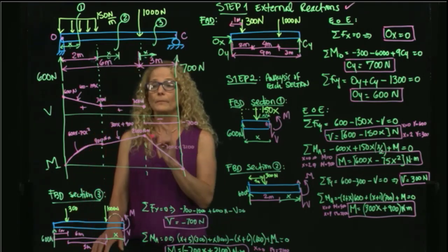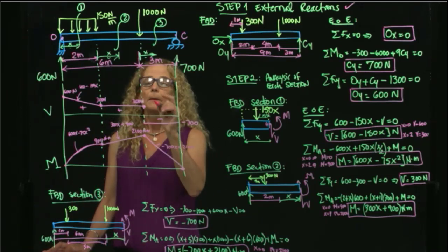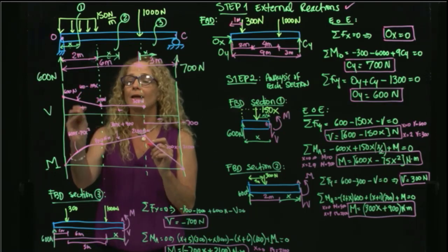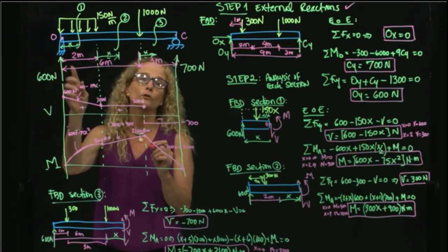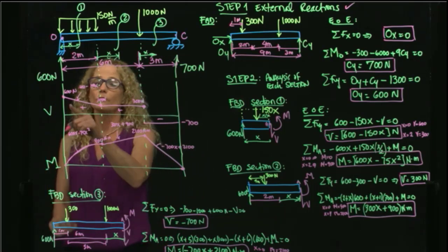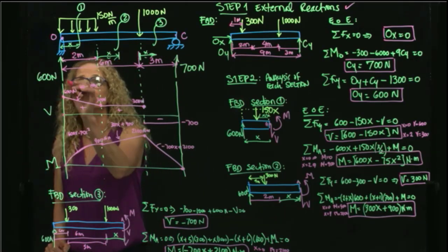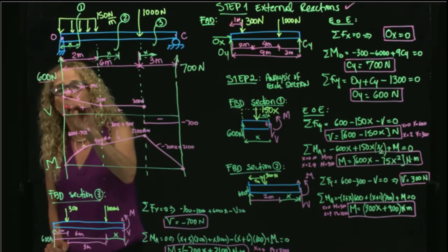Okay, so very important that here we have some discontinuities. I have said many times that anytime we have a discontinuity, we have to check that those discontinuities have the same magnitude as concentrated loads in the case of a shear diagram. So for example, here we have to start at 0, and here we have a discontinuity, and this discontinuity has the same magnitude as the 600.